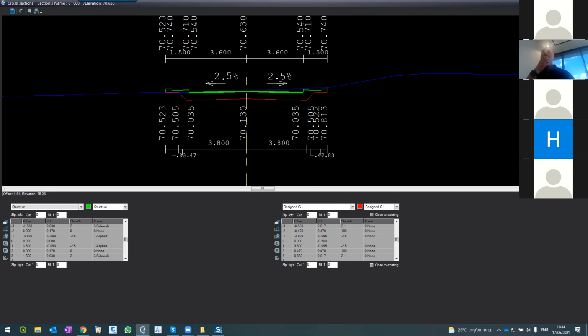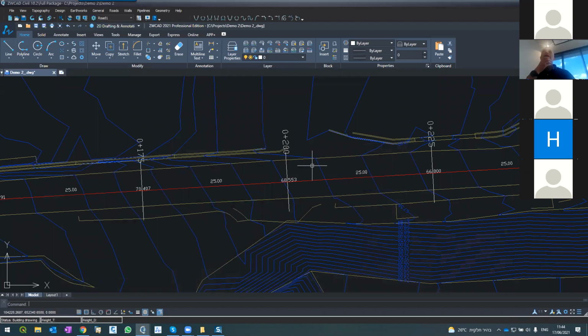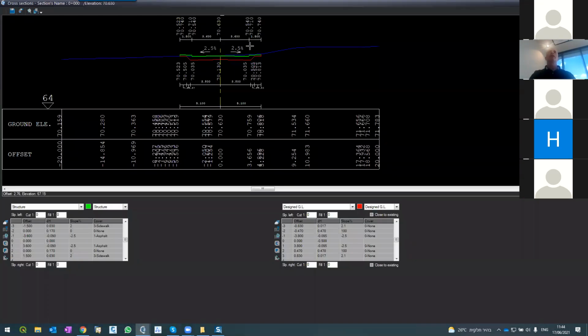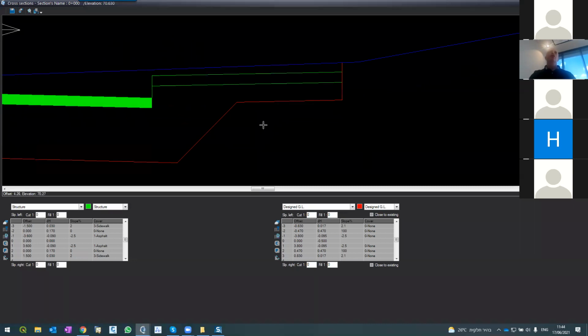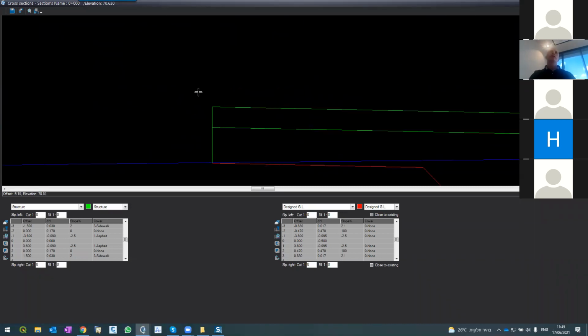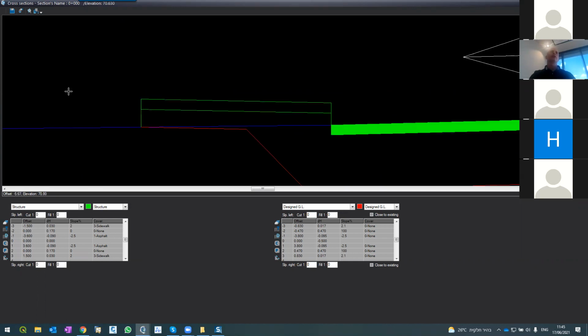Let's say that on the left side, let's look at the layout. On the left side here, I'm just ending the road with a straight either retaining wall or some land development, which I will do here. On the right, I want to create a drainage. Although I may have a collective drain, which I'll have to do here, but here I want to do a protective drainage. Small ditch. So here, the closure is acceptable, because here I'll do land development.